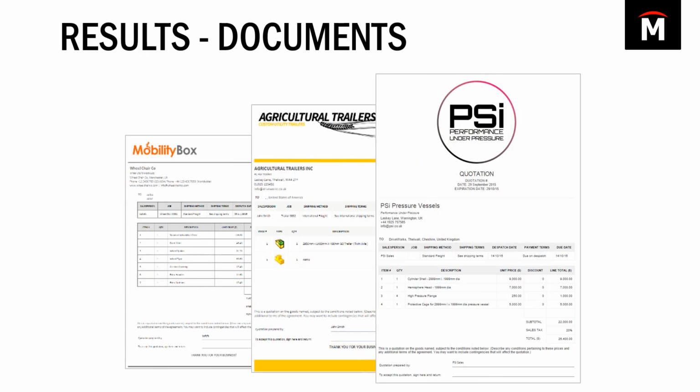Now, Driveworks isn't just about creating SOLIDWORKS parts, assemblies, and drawings. I mean, that's really the bulk of our work, but there's a lot of other documents that go along with manufacturing these custom products. We took a look at some of those earlier, things like quotes and bills of material. But the cool thing about Driveworks is it can actually drive a few other file types. So Driveworks can actually customize and drive Excel documents, Word documents, PDFs, XML files, HTML files. There's a number of other document types that you can build templates for so that every time you run your Driveworks project, it will start to create those documents with every single order.